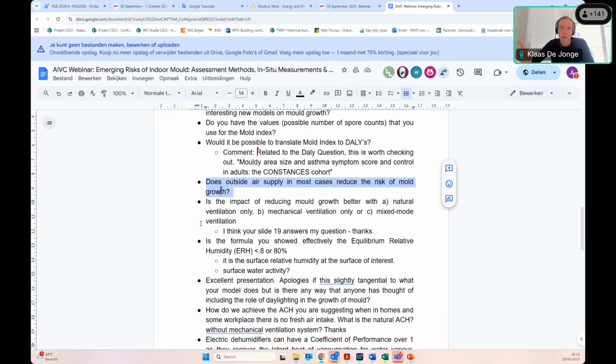Sure. And also if you're cooling or not. Because if at some point you're actively cooling in your buildings because of the climate, and if it's necessary, you're also dehumidifying typically. So in that case, it could be that it's actually not better to ventilate more. But I guess that's just more of a result of the relative humidity and temperatures that you feed into the mold growth model. So moving this methodology to a climate where that's relevant, I think would still make sense.